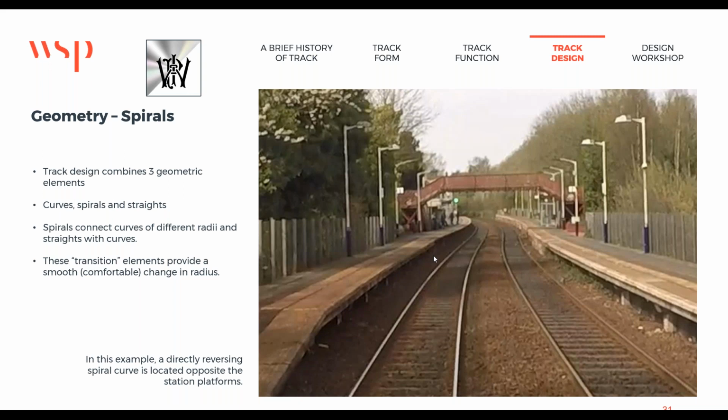It's the impact that it has on track. So if you've got continual top faults in one area, and you think, well, why do I only get them there? I don't get them elsewhere. You might want to look at, it's in the station platform at Giffnock, and it's only at the East Kilbride end, and I can attribute it to the HARP units. But as I said, fixing that problem would then need an approach to the structures engineer to rebuild the station riser wall as a solid unit, or tear the whole platform down and replace it with a polystyrene unit, which they might be doing at Giffnock. Absolutely. I hope that answers the question, Michelle.